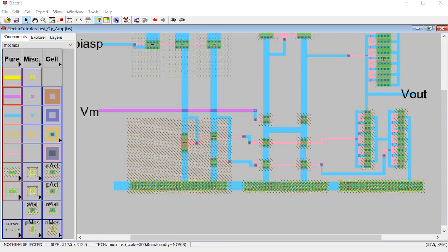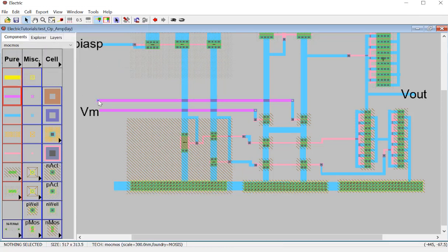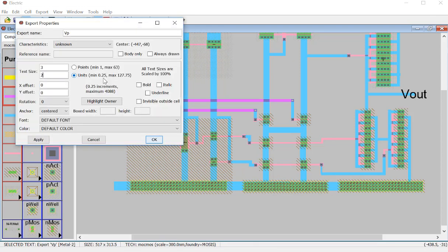How long has it been? Okay, it's already about 15 minutes. So I want to stop this. Let's get this done and we'll stop, right? Come to here. That's a metal 1 to metal 2 connector. We get a metal 1 and metal 2 being extended to the left side of the chip, so it's more convenient when you are connecting this one to the pad.